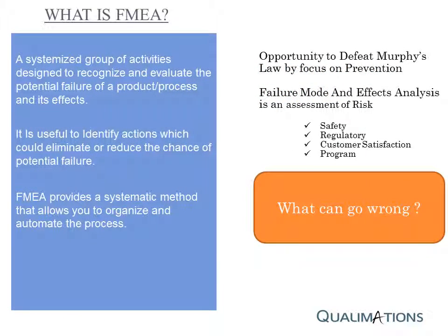The goal of performing an FMEA is to review all of the functions or components of your system in order to determine ways in which a failure can occur, and to define the resulting effects of the failures on your system. Once this is completed, an FMEA can be used to determine the most critical failure modes, and then determine how these critical failures can be minimized or eliminated.